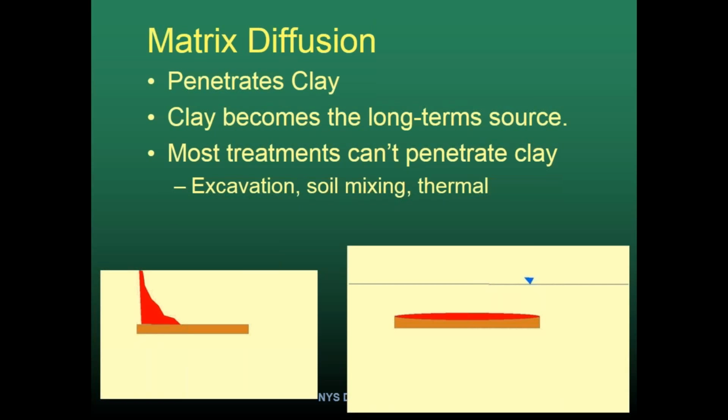One of the descriptive terms they use is diffusion-limited conditions, where the rate at which it back diffuses out of the low permeability material will dictate the concentrations in the environment. Most treatments can't penetrate that clay.